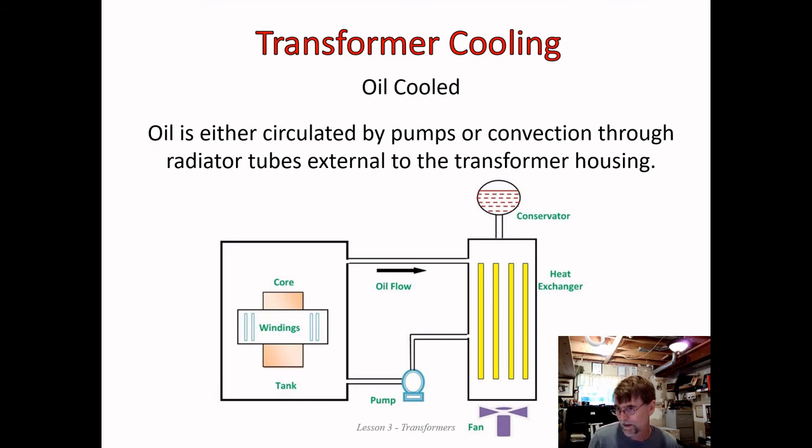We can see that we have a tank, and there are the windings right there, and the windings are actually submerged in the tank of oil, and the pump is moving that oil from the tank to the radiator fins where it can release the heat, and we have a fan blowing up through the fins to get that heat out of there. A very active cooling system, not unlike the cooling system in your car's engine.